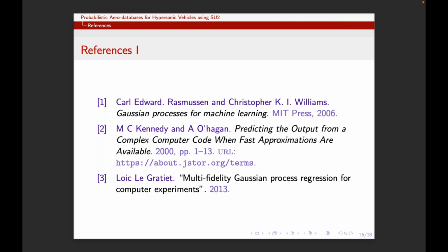Fitting a GP in general is very dependent on getting a good initial sampling to get a good estimate of kernel hyperparameters. So in general, what we're doing in the higher dimensional spaces is we're using some kind of quasi-random, quasi-uniform, like a Latin hypercube type sample to make sure that we're getting a uniform sampling of all the data. And then we may adaptively refine based on the uncertainty and place additional high fidelity samples there.